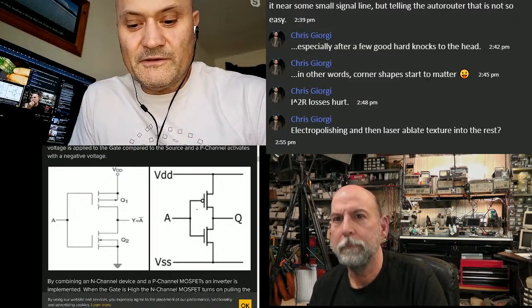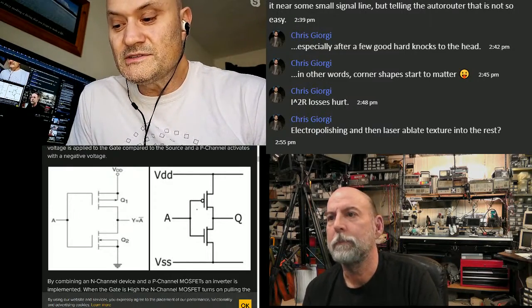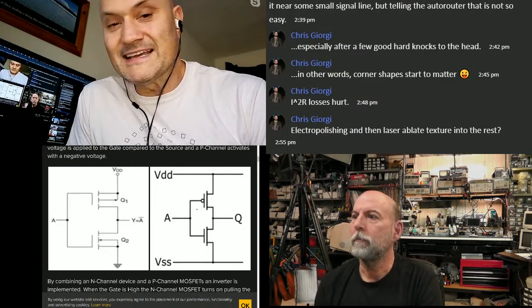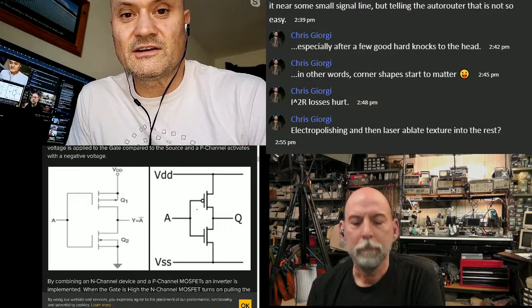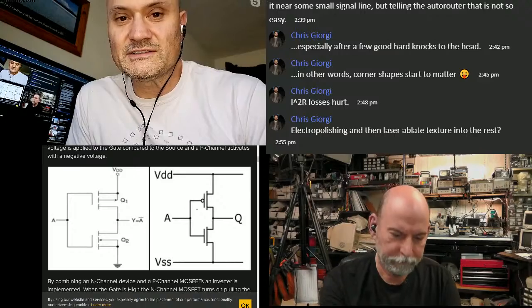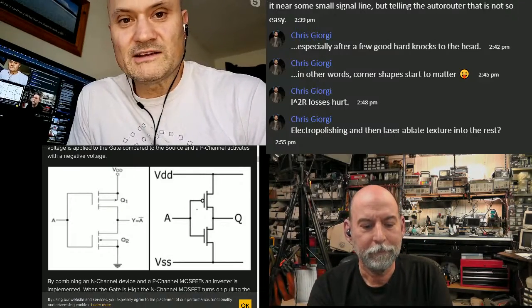It's also, when you're doing your PCB documentation, you should be using fiducials along with any other datums used for geometric dimensioning and tolerancing on your PCB fab drawings. So it's very clear to the manufacturers that this is a reference for everything else, you know.